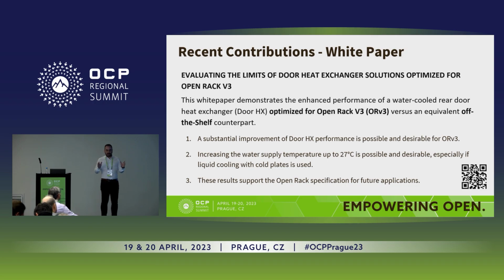We calculated the rear doors in order to improve the performance, by a lot. In order to increase the facility water temperature, increasing as well the air temperature going to the server, but at the same time reducing the approach temperature.